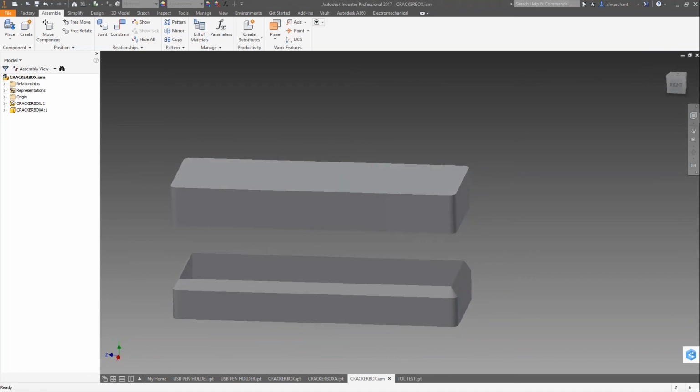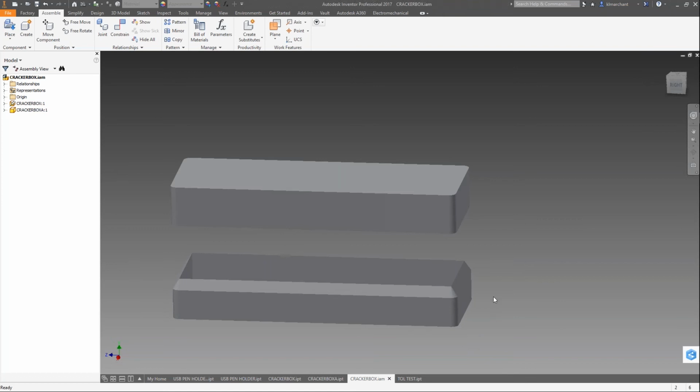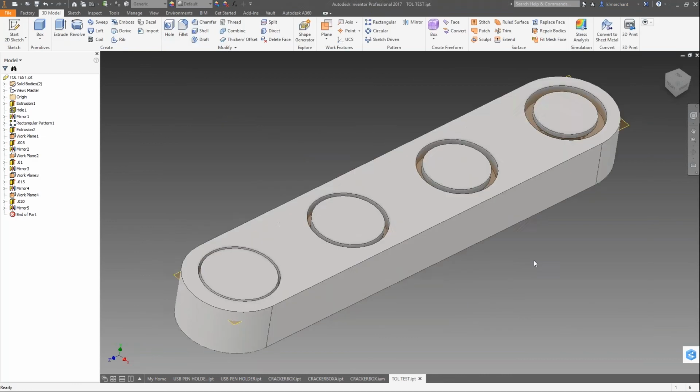A lot of FDM or FFF technology, you'll see nozzle size or print resolution referred to as the diameter of the nozzle. For instance, we can print 0.1 all the way up to 0.2 on some of our printers, and even some of the other printers we deal with get up into very large nozzles for rapid printing at a low resolution. Again, just depending on what it is you're looking for, whether you're looking for aesthetics, strength, speed, quality, all those things fall into there.